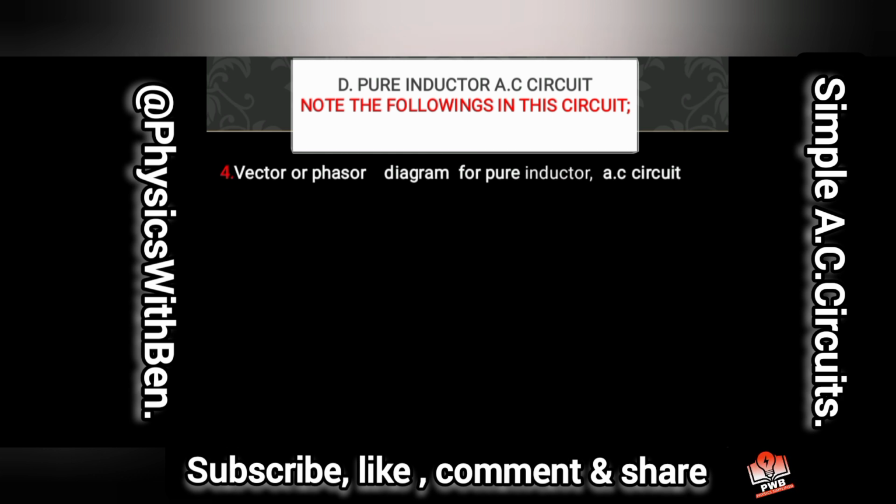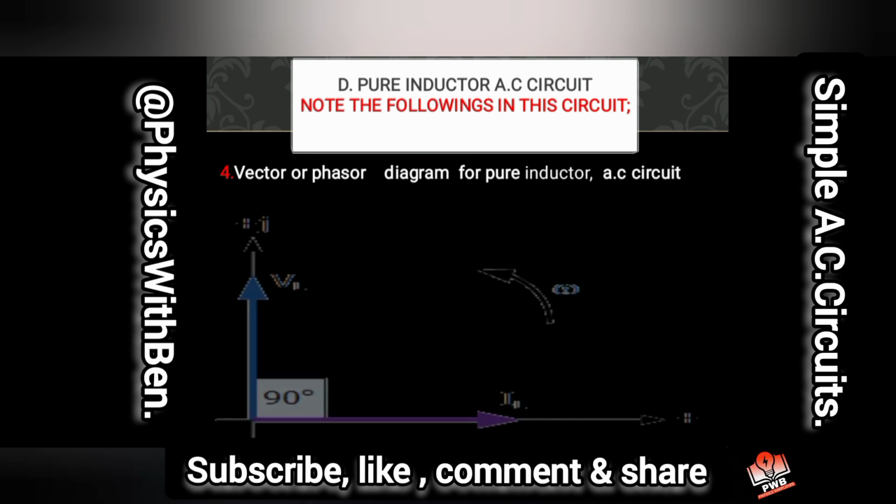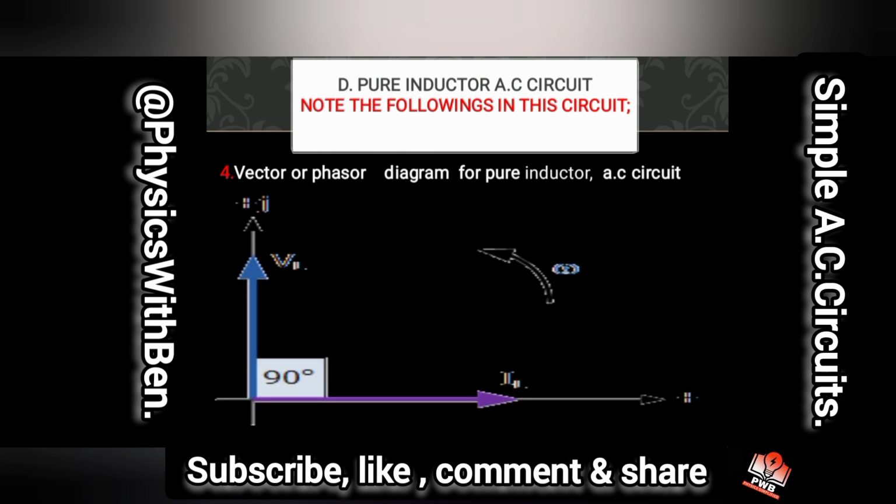The phasor or vector diagram for a pure inductor AC circuit is this. As I said earlier, it is not a must that you draw it like this. Here is your VL, and this is your IL, and here is your omega, the angular frequency or angular velocity. This diagram can also be drawn like this. We can equally draw this as our IL, and this is our VL.